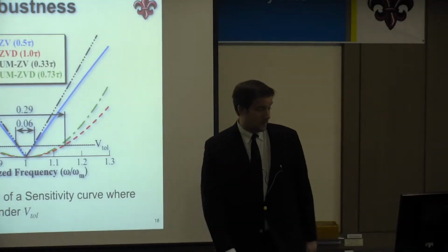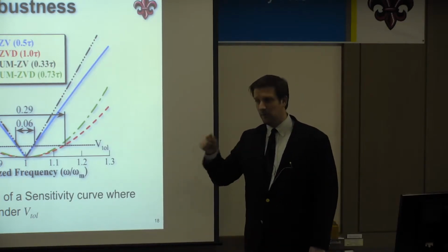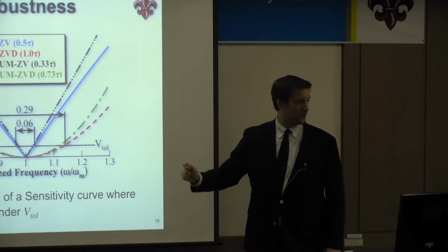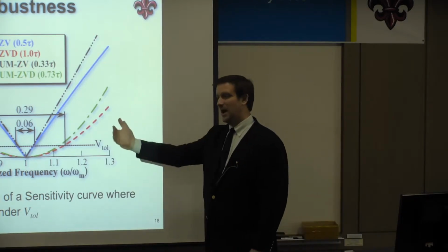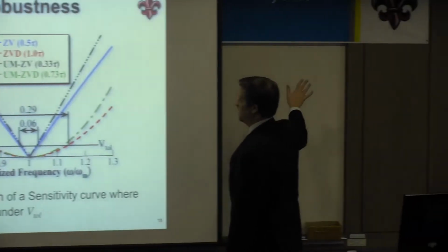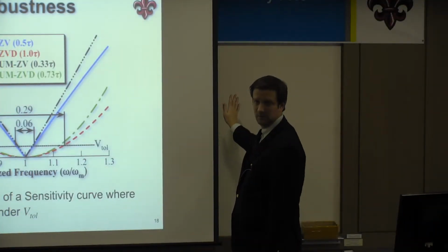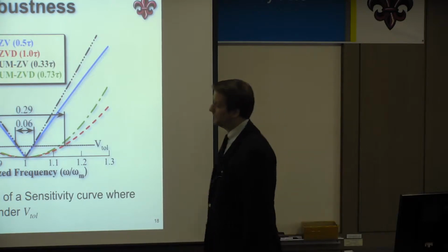One thing to be concerned about with the unity magnitude shapers is you are pushing and pulling your system much harder. So you can excite higher mode oscillation. If you look at the sensitivity curve way out here, the unity magnitude looks way worse than the positive shapers. So it's something to just be aware of.